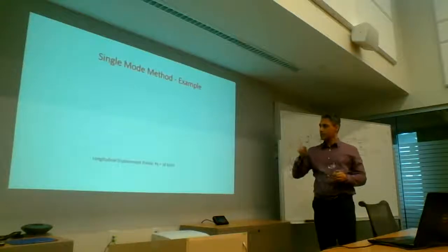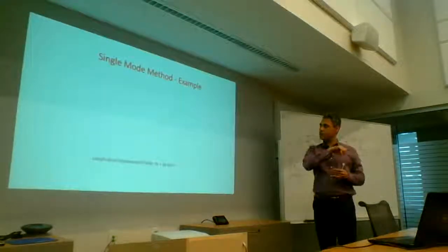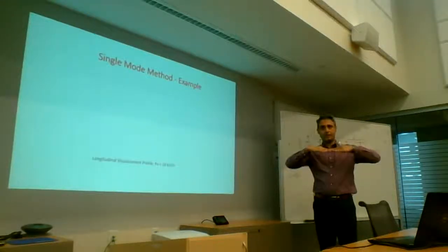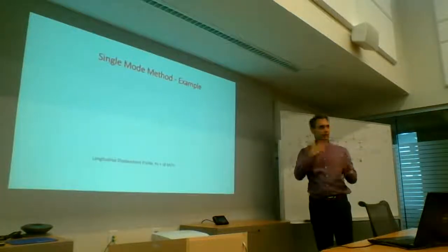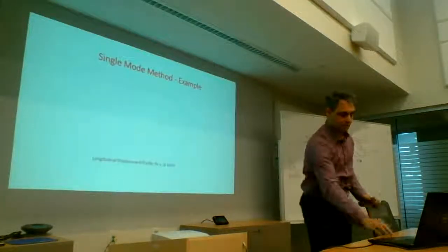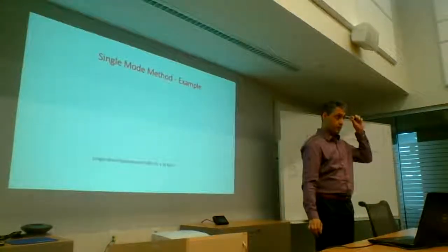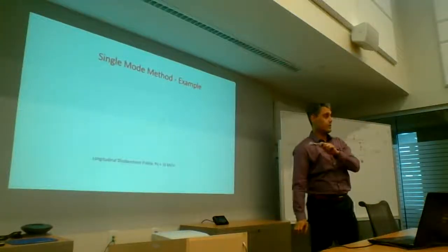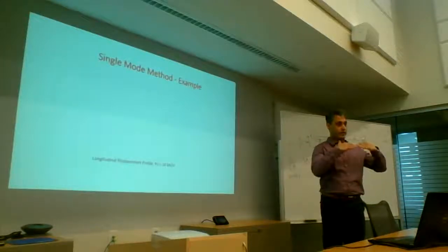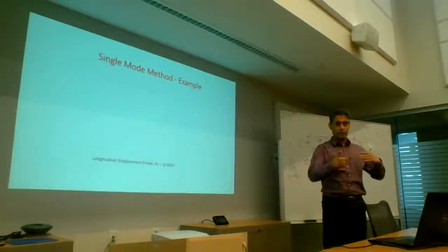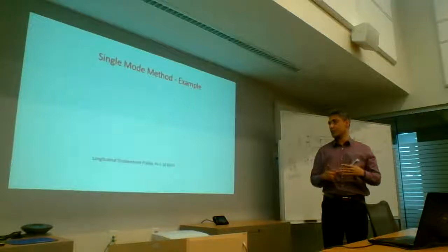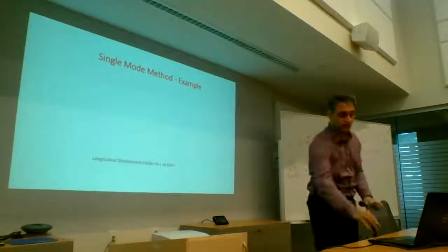So when you put an infinitely stiff stick in SAP, if you bump up the area by a factor of 1,000, all of a sudden the two match very nicely. But you know that that's not correct, and that's what I mean by keeping your mind open. So SAP is giving you the right behavior here because you've got the actual area that it accounts for within its finite element formulation, whereas the single mode method doesn't do that.